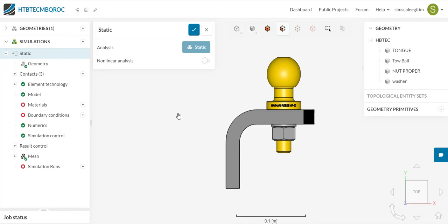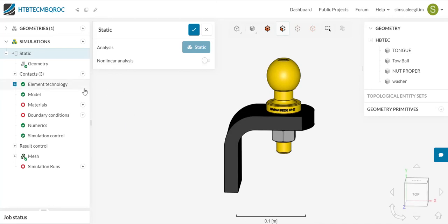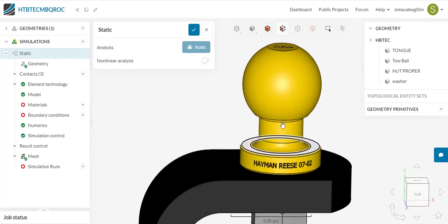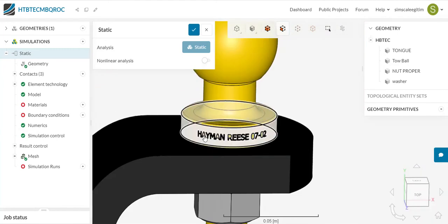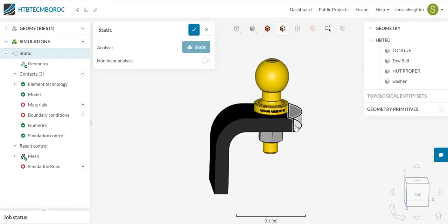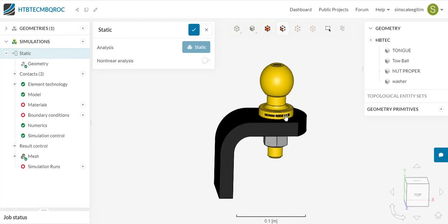There will be some jumps in the video such as the previous one because I don't want to waste your time on doing some simple yet time-consuming operations. First thing I noticed is that the CAD model has unnecessary details. A recommendation: never leave those marks, text, etc. in your CAD model, neither CFD nor FEA, because it will only increase the number of elements in the mesh or the number of nodes, and or it will cause mesh failures.